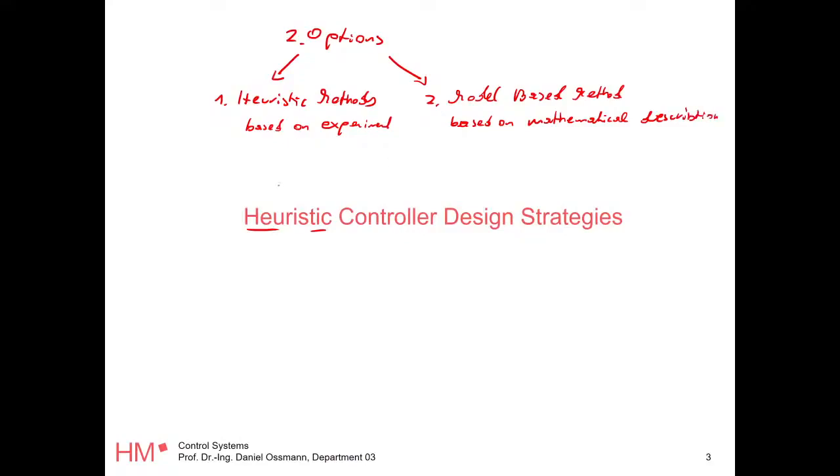So here you really work on your experiment, like this robot here, right? Here you really tune the controller live, so to say. And here you first build a mathematical model, G of s, and then you plug the controller around it, first on paper, and then you see if it's working.